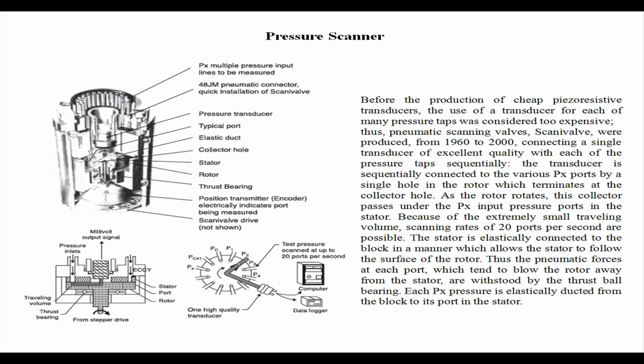If you have pressure leakage, what might happen is that pressure from one port gets to the pressure transducer through a leakage point, which it shouldn't be doing. So, there were enormous issues, but finally the designs which were available from these companies were doing pretty well over so many decades, and all of us who have done measurements with these devices are familiar that they have given us good performance.